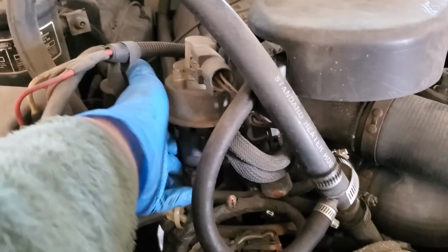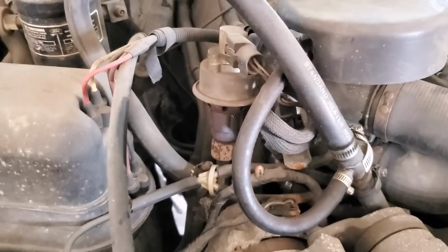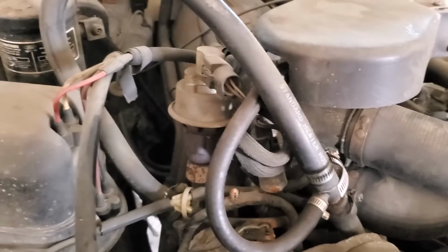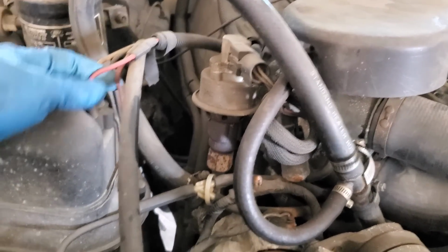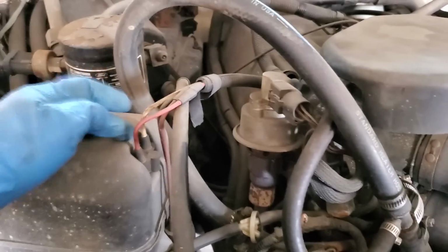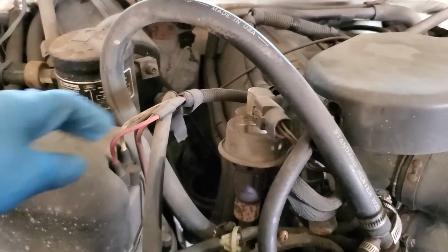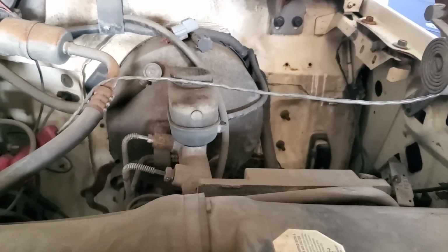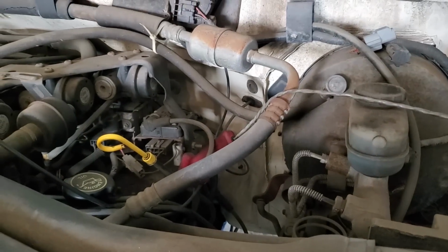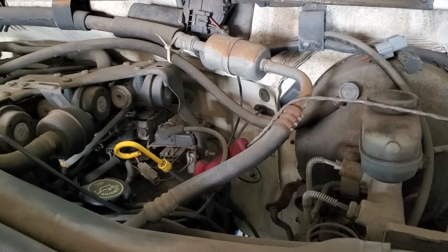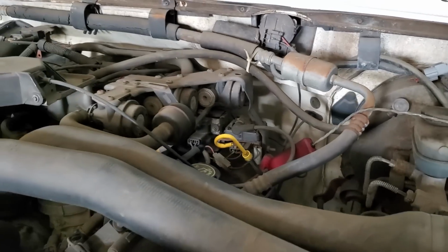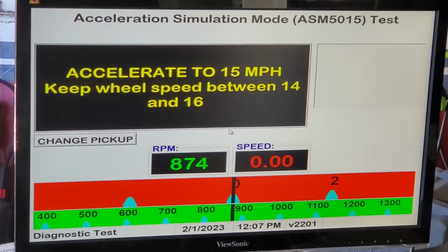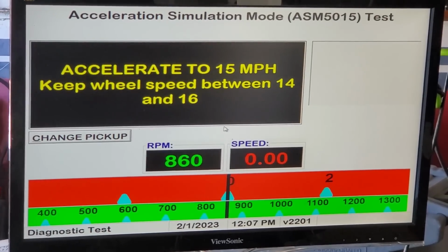Well, the EGR finally did start opening because this is hot as hell now. And it'll set it. These things will set a check engine light in a minute if the EGR is not working. They're really known for these vacuum lines breaking, these hard vacuum lines. So I think we're a success here with this ECU recap. We'll have to try it for a couple days and see if the no start complaint comes back, but this will simulate an actual California emissions test for this specific vehicle.